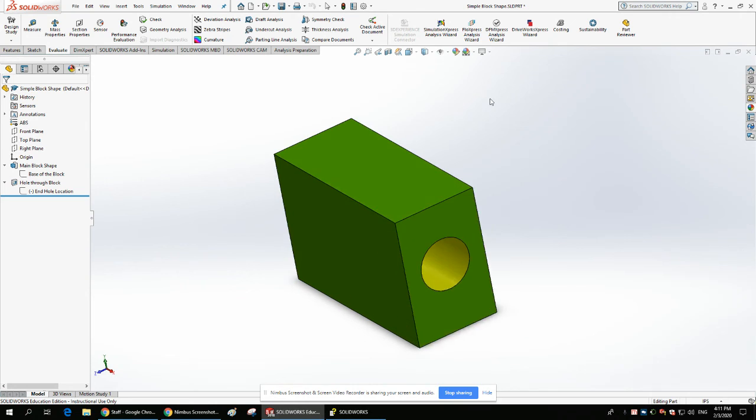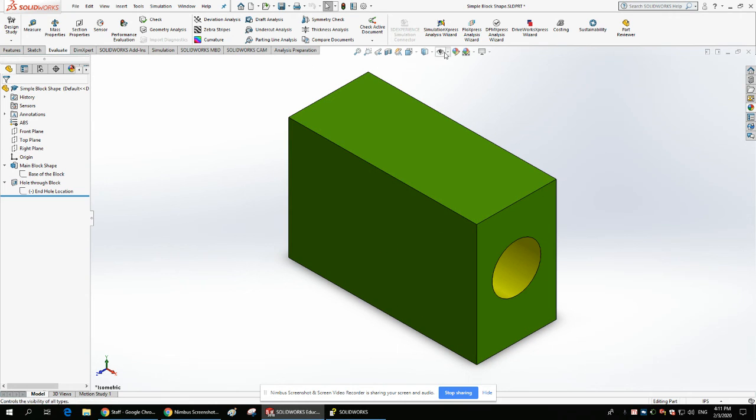So there's some more features to play around with, checking how you view the part, how you zoom around. Remember, always rename your pieces and check out your mass properties based on what you set as a material, and then you can change some colors if you want for your style. That's it. I hope you're learning. Thank you. Oh, forgot to save. Don't forget to save. Yep, save, and now we're done.